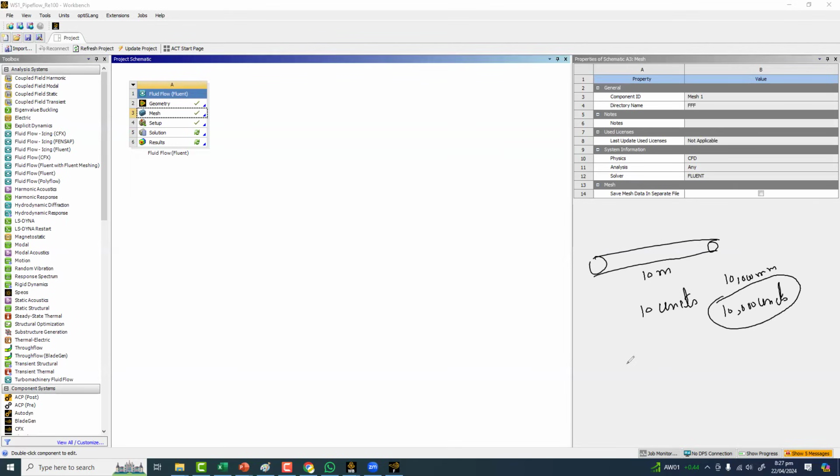But the problem is that Fluent, because it has to keep the dimensional quantities intact, is based on the SI system. So it will always work in meters, seconds, kilograms, Kelvin, like that. Whenever any data comes to Fluent, its internal working will always be based on the SI system. You can input data in other systems, and you can get the data output displayed in other systems, but the internal working is based on the dimensional values of the SI system.